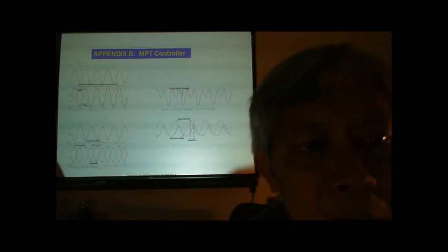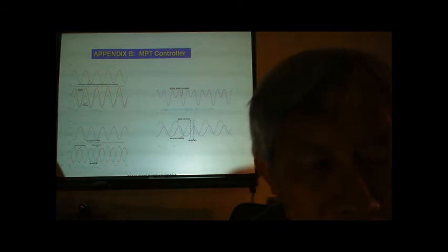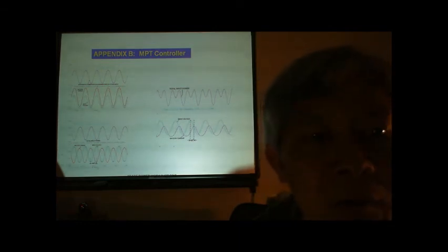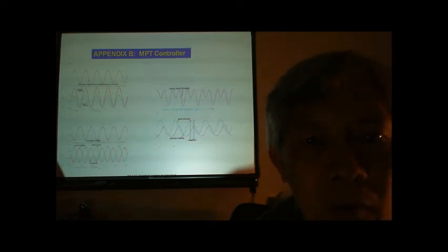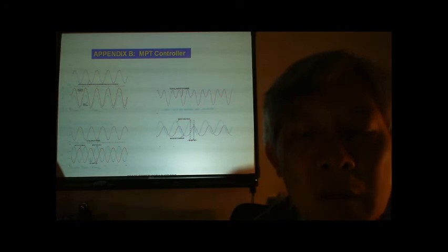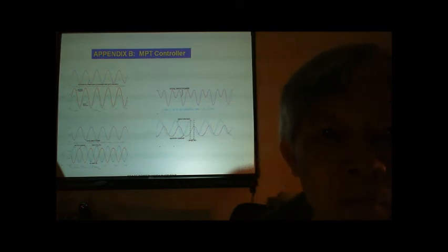When both the power signal and the solar array or sourcing voltage ripple are in phase, this corresponds to the operating point when the operating peak power is on the left side of the PV characteristic with respect to the peak power point.